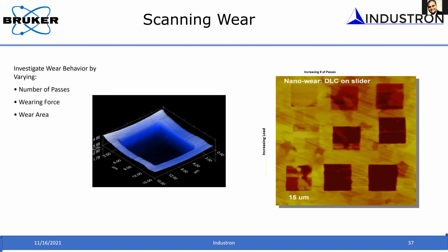That will give you an understanding about the tribological property of the materials using a similar setup. Okay, and along with material removal, you can also figure out the friction characteristics through a friction map, through the lateral force sensor. So in a way, it's not only measuring hardness and modulus. With this in-situ SPM imaging capability, with a 2D transducer, we can also do tribological characterization of the material.